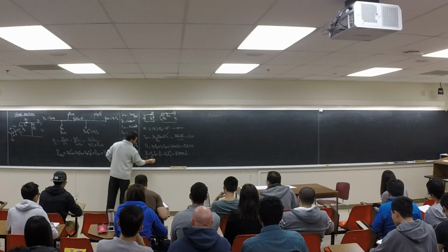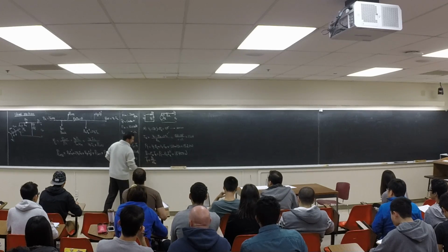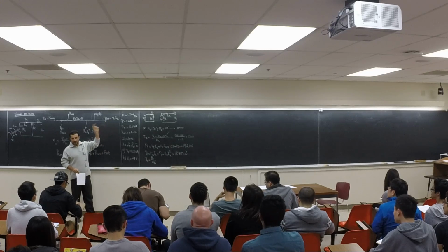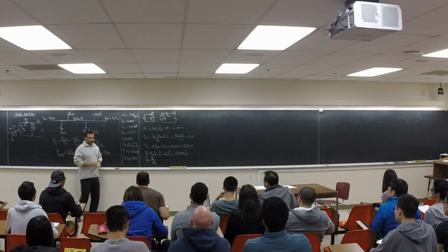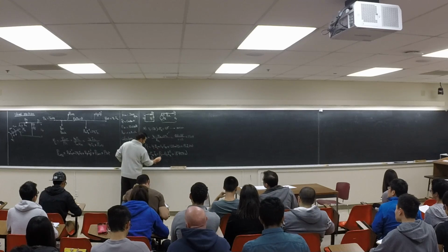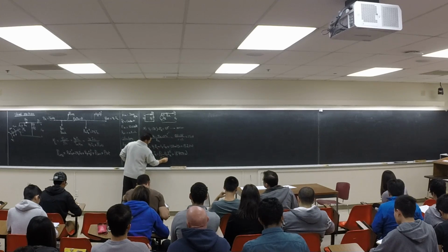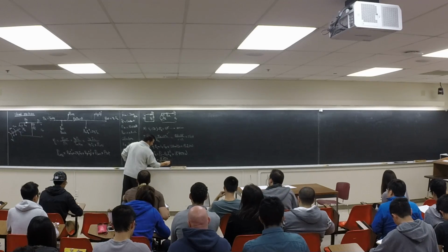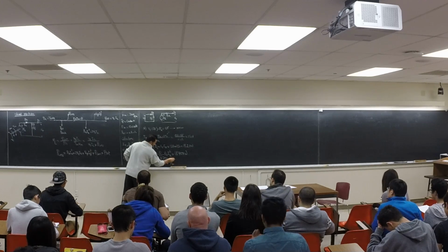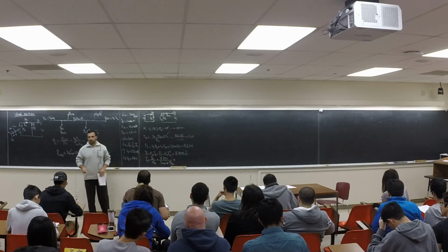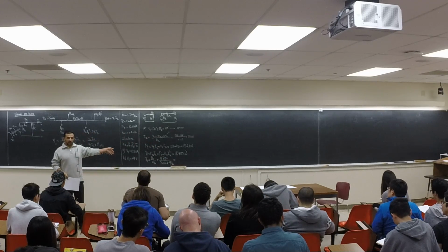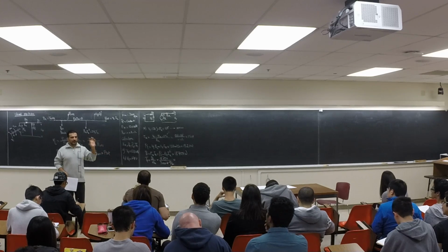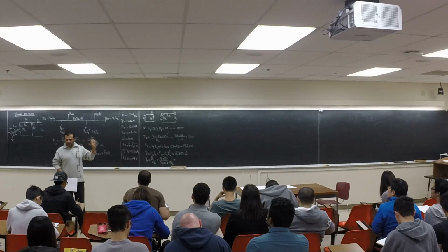TE is P over omega, right? So how much is omega? It's 3000 RPM, and you have to change it to radian per second. So this one is going to be 18750 divided by... to change the RPM to radian per second, first you divide by 60 to get RPS, the rotation per second.